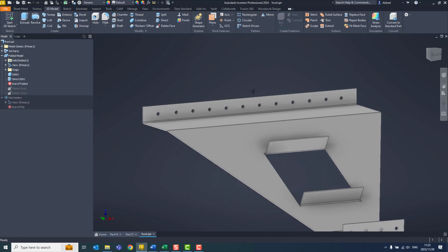Once you've brought it in, even though we don't have all our features like the extrude or revolve or actual hole wizard that comes from another package. So if you are doing a lot of Sheetmetal components which are coming from somewhere else, and it's either a step file or a competitor package to Inventor, then you can just use the direct edit to manipulate it.